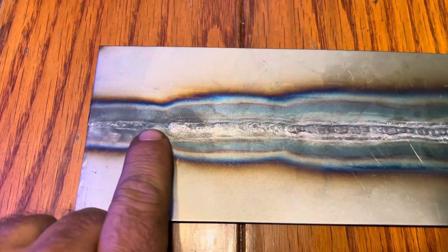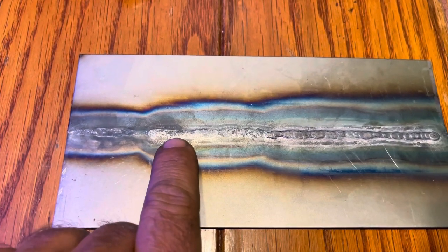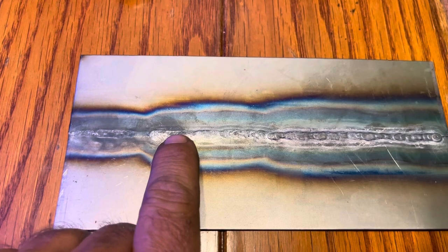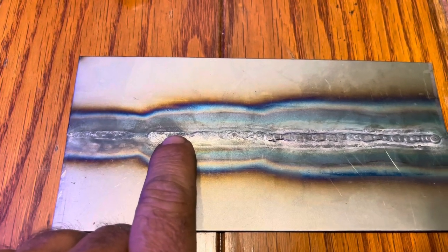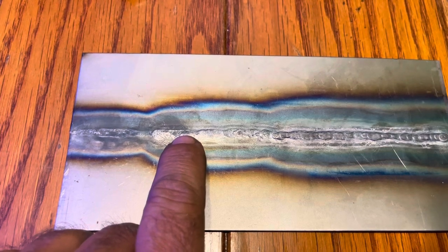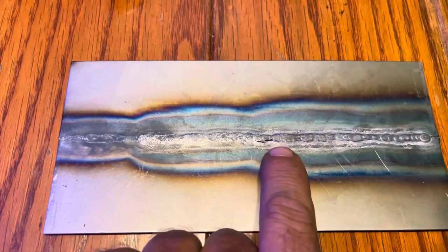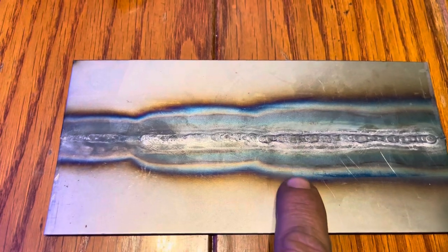But it's very obvious that when we were just fusing it, the puddle stayed one temperature. And then when I was adding filler wire, it took longer to heat it up to keep that puddle at the right temperature because I was adding a cold filler wire. And that extra time added more thermal conductivity. And then with the great big wire, it was even more.